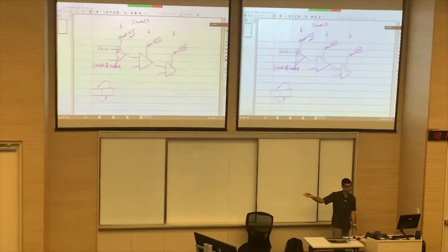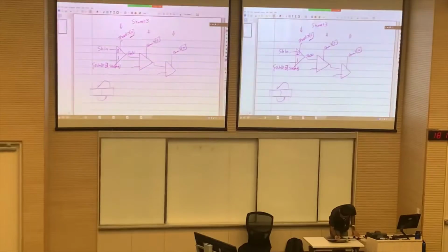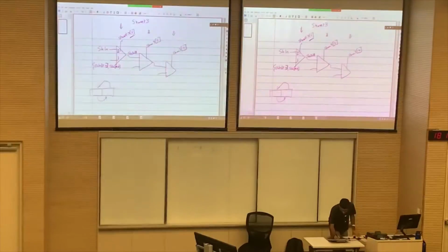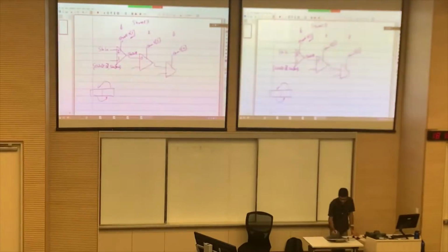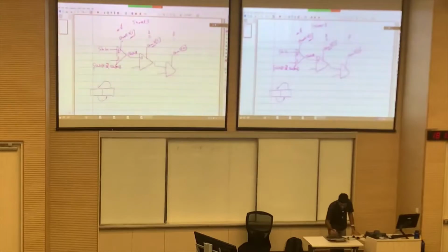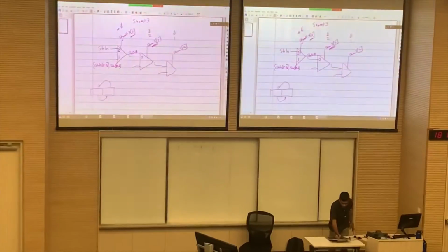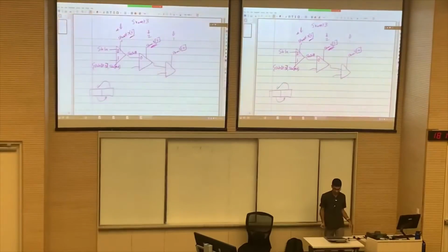And now we know where we are getting, right? And let's say this is SH out A. SH out A will be passed as such if we don't rotate by an amount 2. So here it's rotation by 4, rotation by 2, rotation by 1. So if this middle order bit is 0, it means you don't rotate by an amount of 2. How about here?